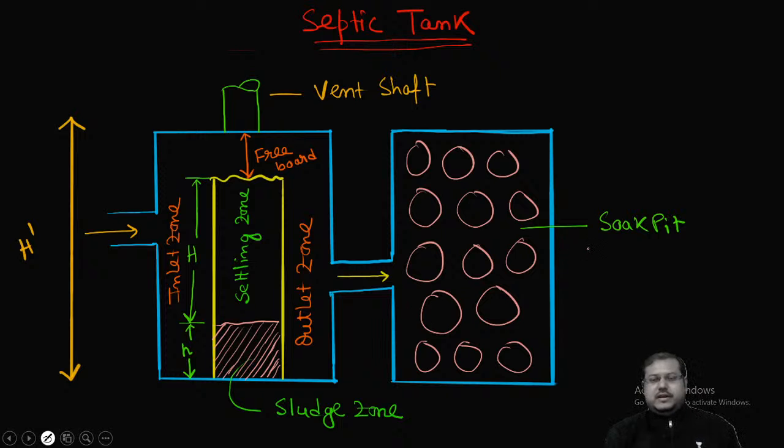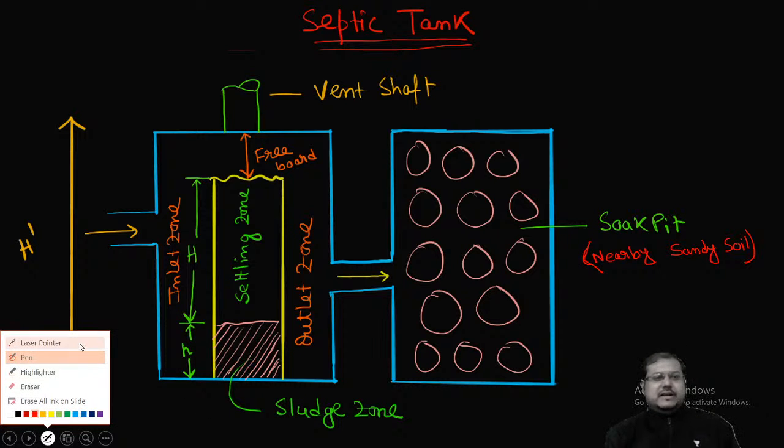So soak pit is actually nearby soak pit, where particle free water will get discharged to the soak pit, which is nothing but the nearby sandy soil. Okay. And we know in the digestion of settled solids, as it is an anaerobic process, certain gases will get evolved.